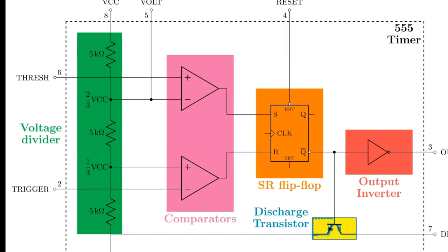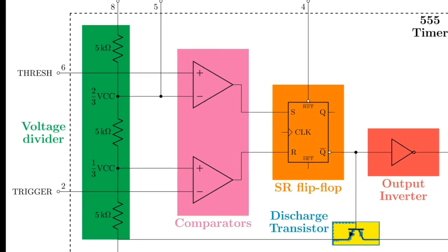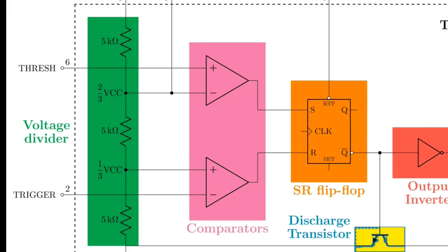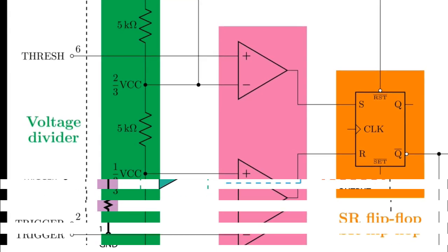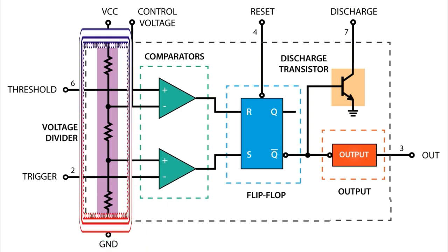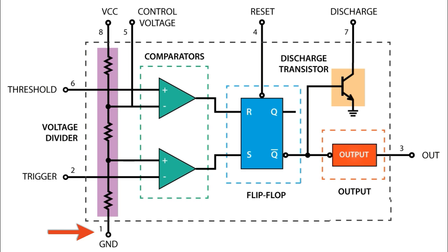As we mentioned earlier, the name of the 555 timer comes from the fact that there are 3 5K resistors that are internally connected to each other in this timer. These resistors make a voltage dividing network between the supply voltage, pin number 8, and the ground voltage, pin number 1. The voltage across this network of series resistors keeps the negative inverting input of comparator number 2 at 2/3 VCC and the positive non-inverting input of comparator number 1 at 1/3 VCC.